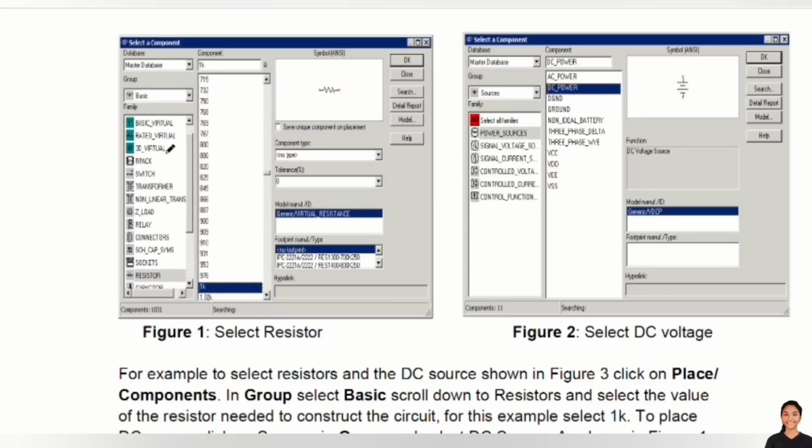Or else if you want to select a resistor or a capacitor, then we have to select Basic and then search for the resistors and the capacitors. If you see this diagram, here you can see the capacitor, the basic components which are required for basic circuits, not very big circuits. For simple circuits, just select, before this we will get an All Groups symbol. In that, if you press this triangle, then select Basic and then search.